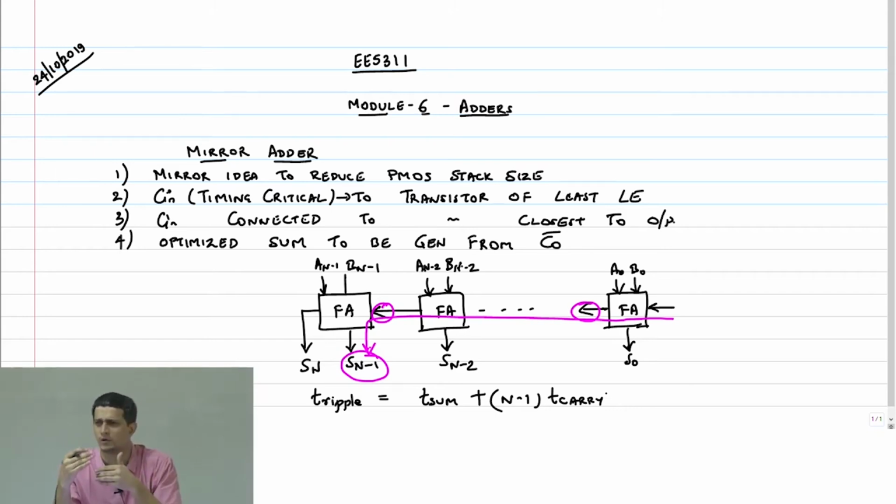Today we will see a few more alternate circuit implementations. Just briefly, I'm not going to go into the details. I'll just show you the circuit, maybe a quick analysis, and I'll tell you what the key advantage of that circuit is. Before we go into that, let us also figure out, when we mark this critical path, in what mode should each of the n adders be in? Should it be in generate, propagate, or delete mode?